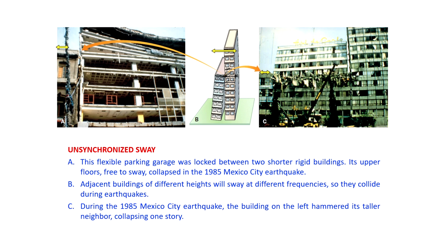Another issue, as we have discussed, is that each building, based on its height, whether taller or shorter, has a different period of oscillation. Without a proper understanding of this, construction in many areas across the world has been done side by side without leaving enough space between the buildings.